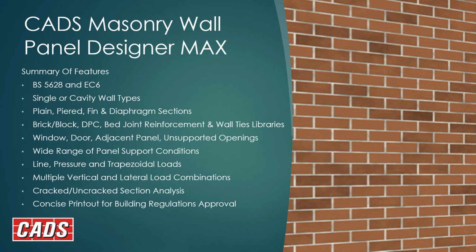Load combinations are automatically created, combining up vertical and lateral loads, but the user can either edit these or input your own combinations if you wish. Walls will be analyzed as cracked or uncracked. This really depends on the nature of the wall you're designing, but we find most local authorities would require a cracked section analysis for more conservative results.